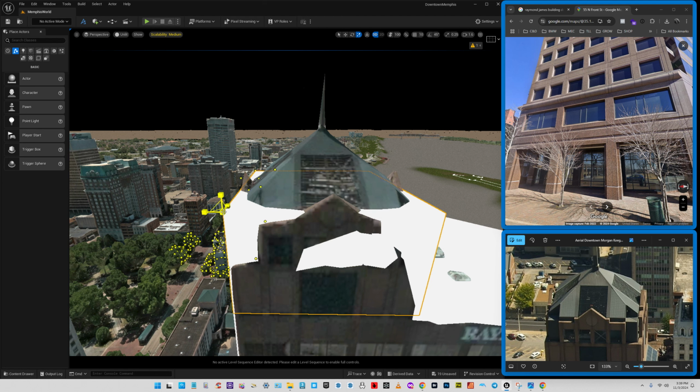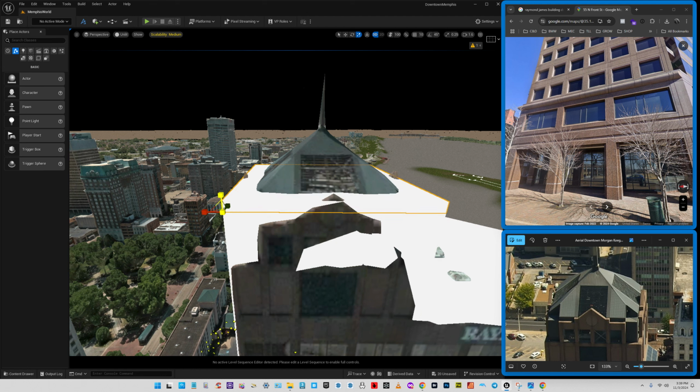I'm gonna move this over to this top corner, this little pivot, using our 3D snapping helper. We're gonna Control D to duplicate, and then we're gonna inverse, pull this up, and this will give us the tip of that.